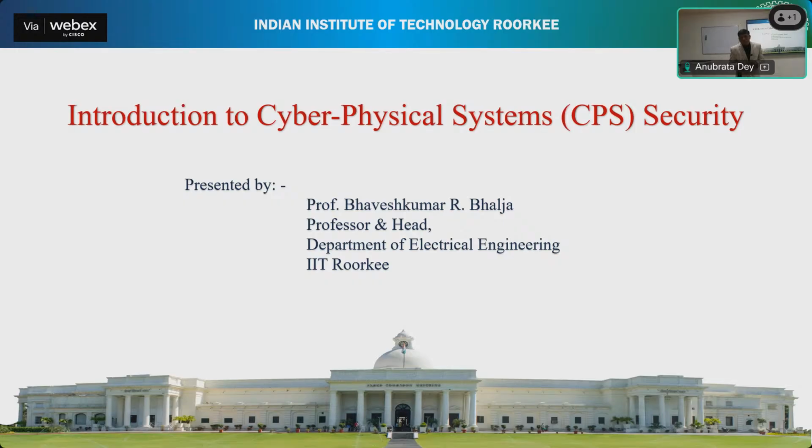But these PMUs are not being used for any detection part or any other part. They simply remain idle, just taking the data. That's all. These PMUs are not used for any decision making. Still, in our country, all decisions are taken based on SCADA-based systems only. However, as time progresses, in the upcoming 3-4 years, decision making will obviously be done based on PMUs also.